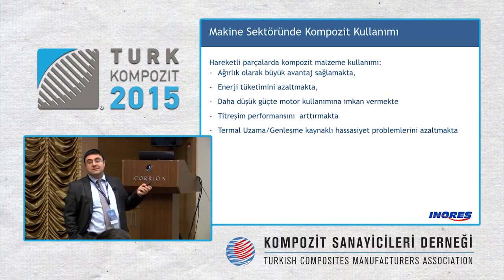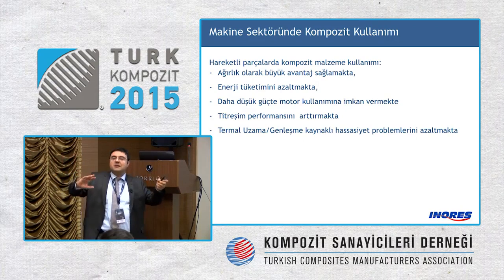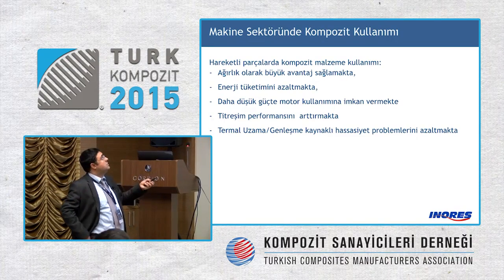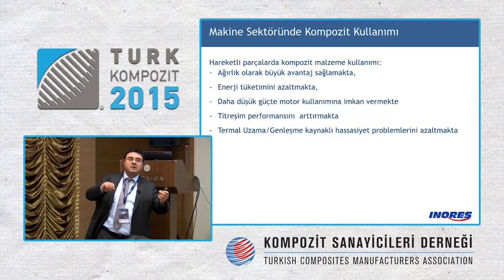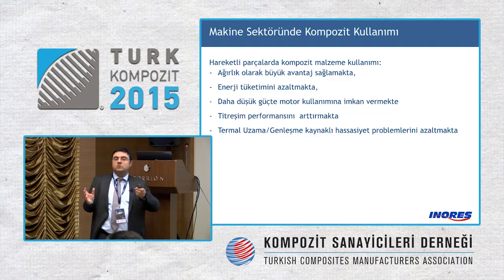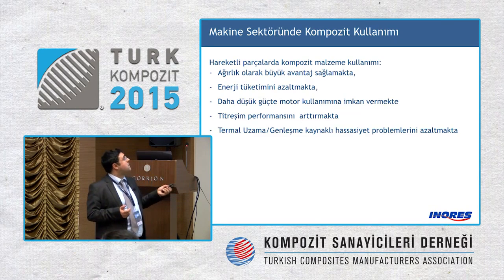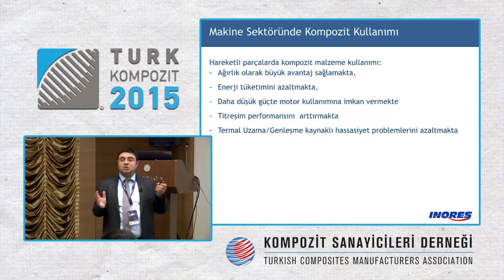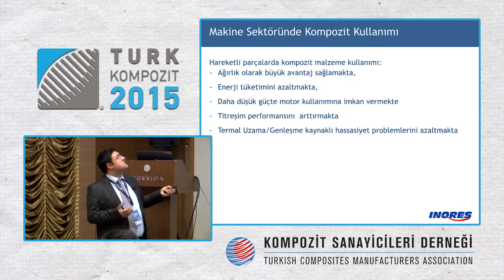The moving parts: composite is used for moving parts. Of course, there is an advantage here because it gets lighter. The energy consumption is decreased, and in order to decrease the energy consumption, you can use composite materials. The vibration performance increases. As I said before, the damping factor can be adjusted and you can increase the vibration performance.